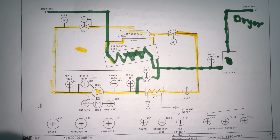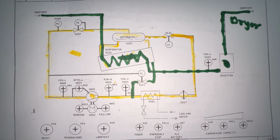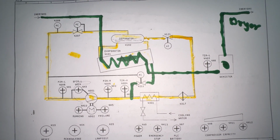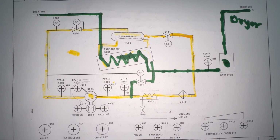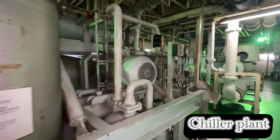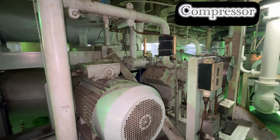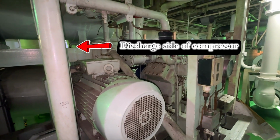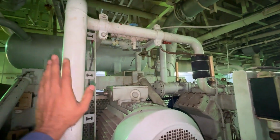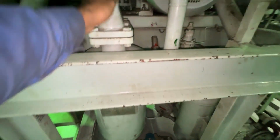So this is the basic mimic diagram of the chiller plant, where IG is passed through the chiller plant so that its humidity gets removed. This is how the chiller plant looks, where we remove the humidity from IG, and this is the discharge side of the compressor. So R22 gas from the discharge side of the compressor will flow to the separator.